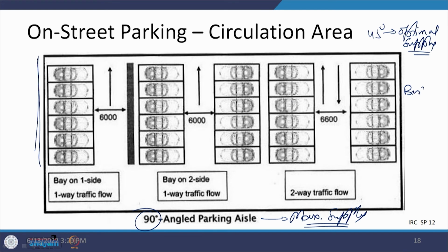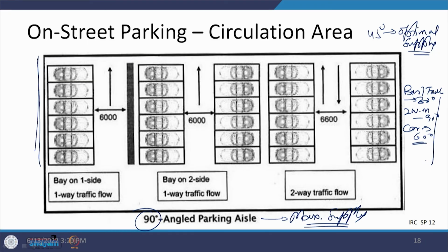Say if you have a bigger size of vehicle, a truck or a bus, then for that bus or truck maybe 30-degree is going to be more conducive. If you are talking about a motorized two-wheeler, then 90-degree is also going to be good enough. That means they are being parked perpendicular to the curb. If it is a car, then 60-degree looks to be more conducive for that. Even 45-degree can also work.